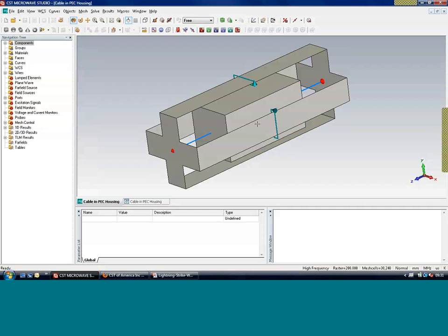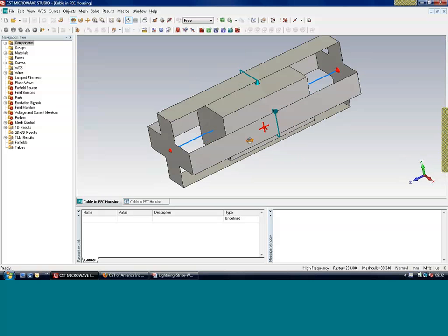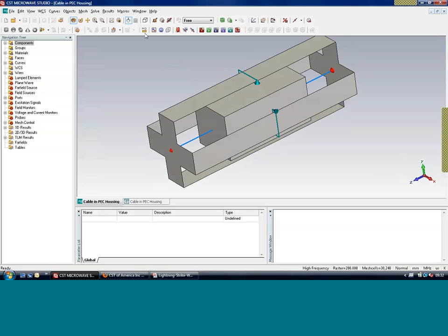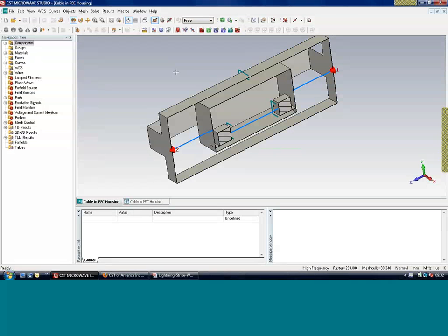Now, when we do the analysis on the ground, typically we would set the structure up. In this example, it's this box in the middle here, which we're going to apply the strike to, and we've got a current return cage around the box. When we do the strike analysis in reality, we've got to have this return cage to inject the current and have the return path. Now, the way this model's set up, I'll show you what's inside the box to start off with.